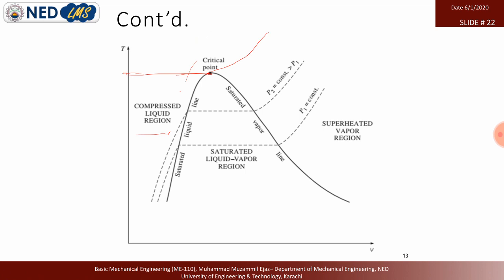The fabrication and overall equipment cost becomes higher when running at that much higher pressure, because we have to use extra material to hold that pressure, and it's also a very critical job. If anyone, due to any negligence, lets that pressure abruptly release, there can be a blast in that area.